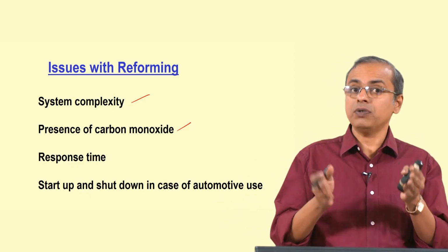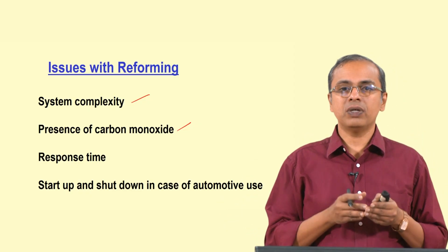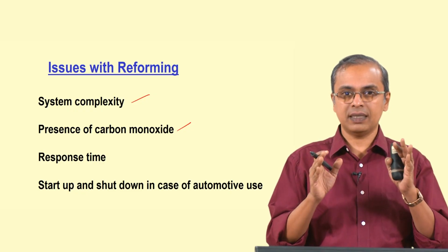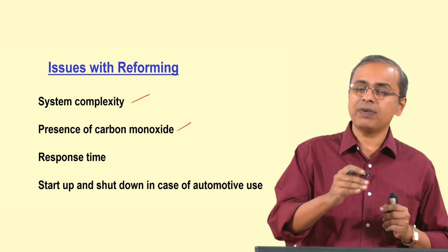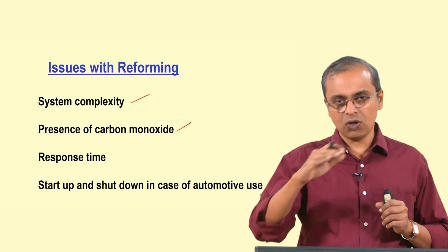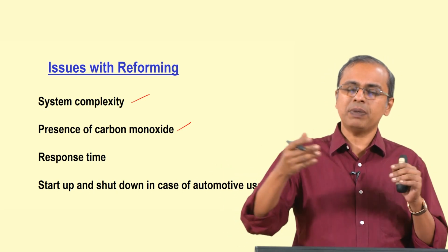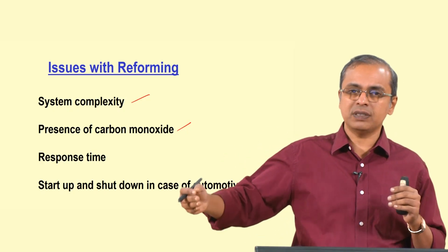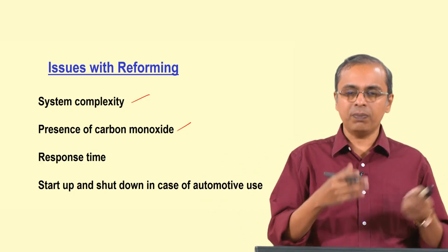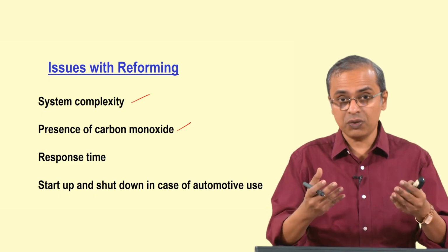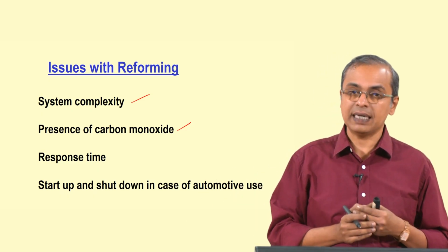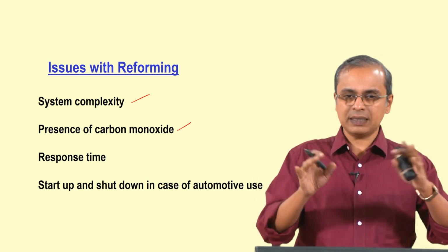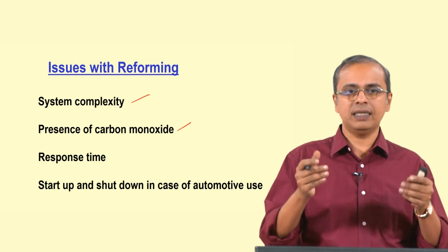And so, we are doing something to deal with the carbon monoxide that is coming off the stream through the reformer. And even then we are not completely done with the carbon monoxide, we just drop it to several ppm, because beyond that it becomes difficult. The more you try to push it down towards 0, the more energy and time and complexity you will start putting into the system just to keep moving it lower and lower in content. So, you stop somewhere and you make some accommodation for it and you handle it and go.